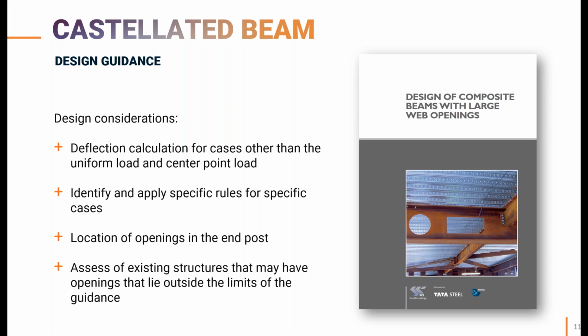Although the problem is well defined, and a lot of work was done to extend previous guidance from the SCI, again, it is clear from the text that a lot remains to be done by the designer, as designers need to consider the correct deflection calculation for cases other than a uniform load or a central point load. Designers need to identify specific cases and apply the modified design provisions, which may be significantly different between design iterations due to geometry changes, especially in the location and the type of the openings.